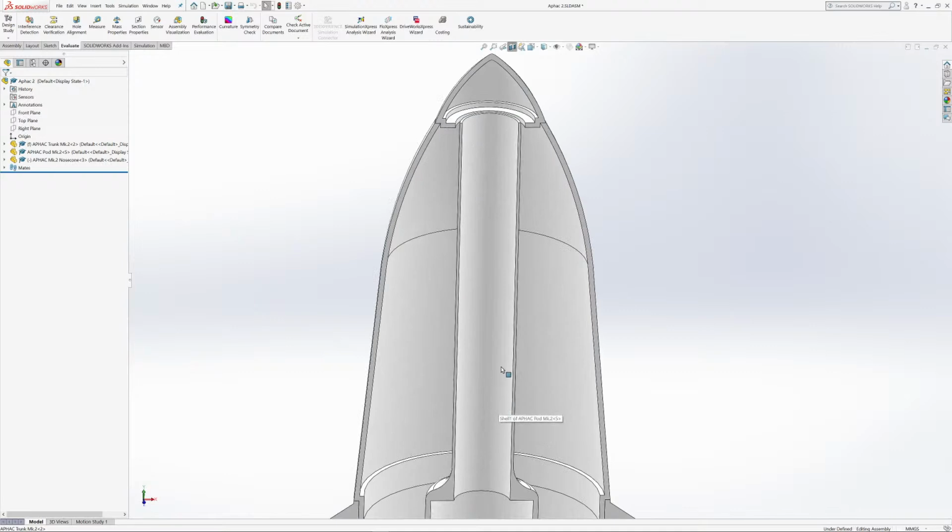So what it's going to do then is we'll have some recovery wadding, which is basically fancy paper. It's kind of like a stuffing paper, not wrapping paper, but like the paper you put in gift bags, basically to hide what's inside the gift bag. And what it does is it acts as a buffer, so that it burns away under the hot gases coming from the exhaust, but it pushes up and helps push your parachute out without your parachute getting completely scorched, which is bad if your parachute gets scorched.